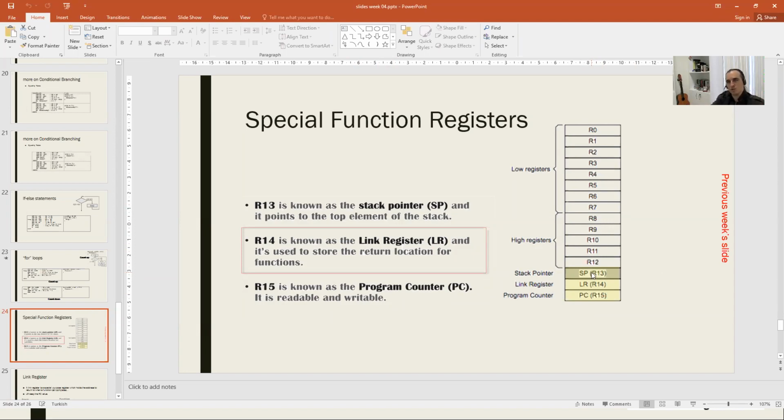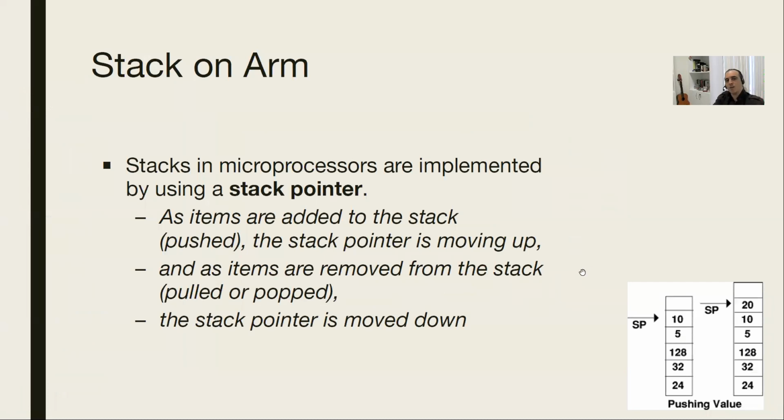It was a bit quick, but we are going to get there. So it's the stack pointer. How come? So guys, actually, you have a part of the memory which is dedicated to the stack. And a pointer is pointing to the topmost element of the stack. So this is the stack, for example. If you push a new value, it will be inserted on top of it, right? Imagine I'm going to push 20. So it will be pushed here. The stack pointer will now stop pointing to this and it will be pointing to this.